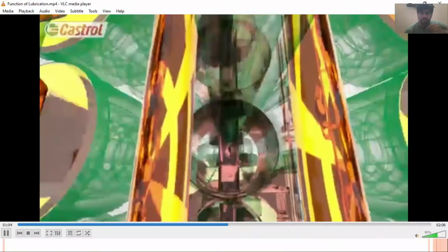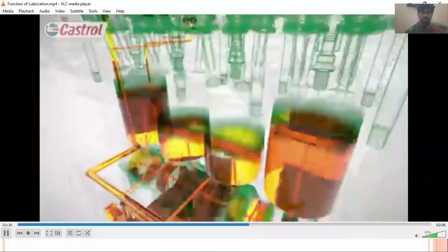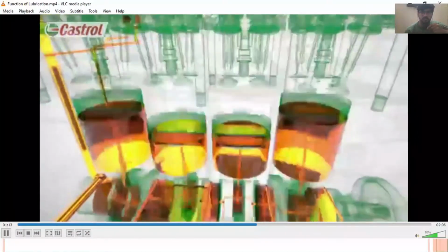All of these are moving components, rotating and reciprocating components, so lubrication is necessary in these components. Therefore lubrication is required between these moving components. Loads in the valve train are the highest in the engine. This is where the oil experiences the most stress. To avoid friction and damaging wear, these fast-moving metal components must be lubricated.